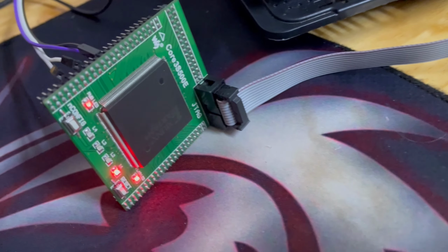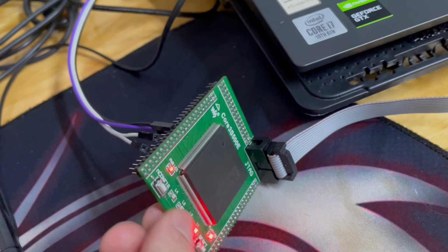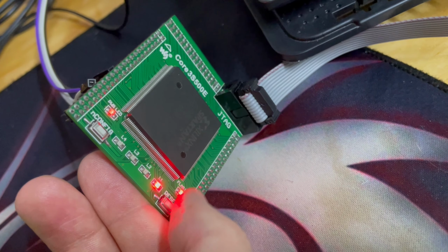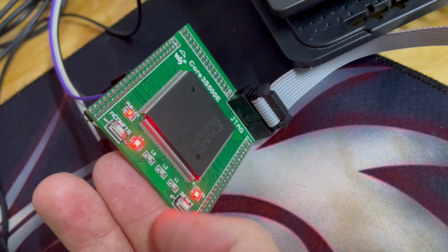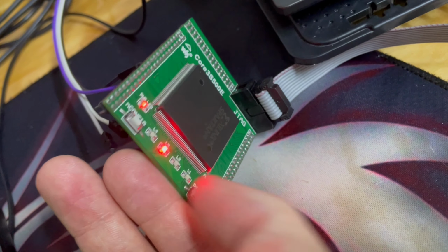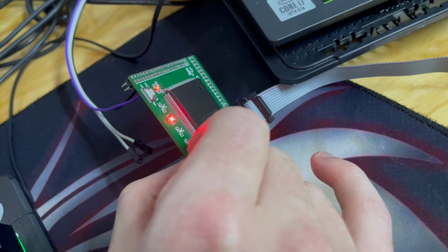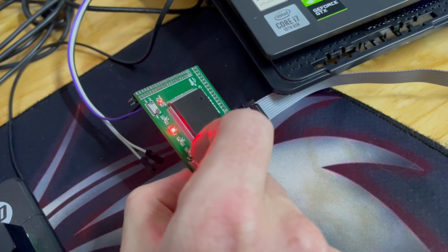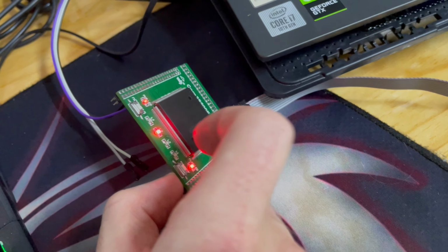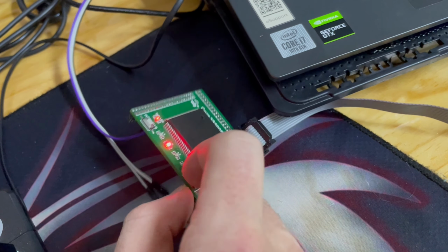So here you'll see the chip is currently programmed. We've got one LED on, and every time we press this reset button, we want it to increment the counter, right? And there we can see it move to the next LED. The second one, it's not working as nicely. And the reason why it's not, oh, there you can see it did some weird stuff right there. It jumped a few LEDs. The reason why that happens is because of a bouncing problem on the reset button.